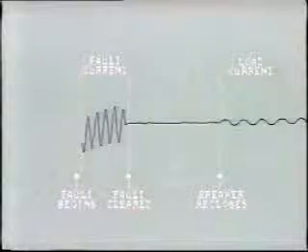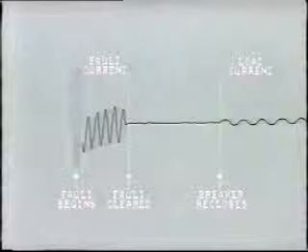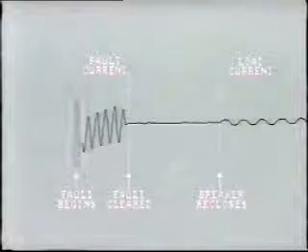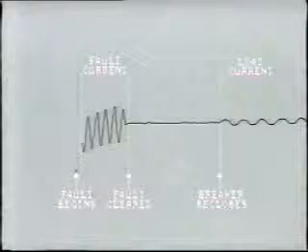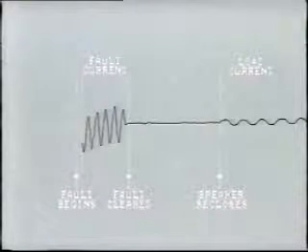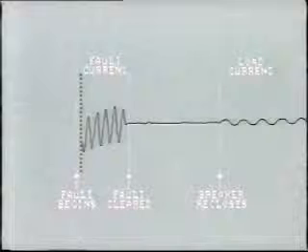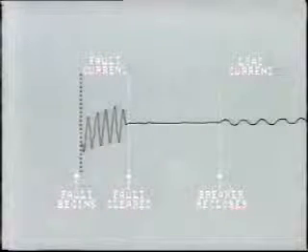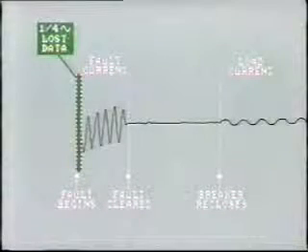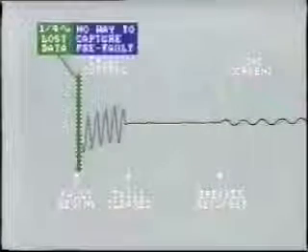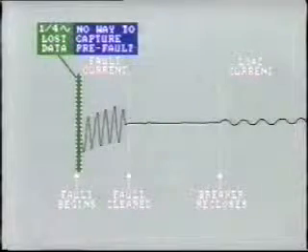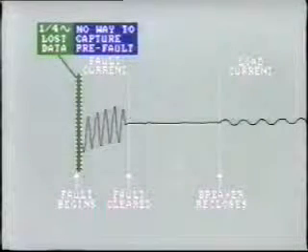The quick start oscillograph is the simplest type and uses a high-speed recorder. As soon as a fault is sensed by a protective relay or other sensor, the machine starts and the paper begins to move after 3 or 4 milliseconds. Of course, this presents a problem since the data at the very beginning of the fault is lost. The loss amounts to about 1/4 cycle of data. Also, there is no way of capturing the conditions on the system just prior to the fault.